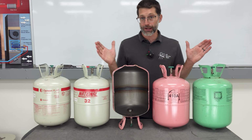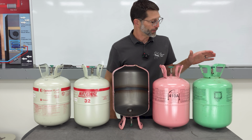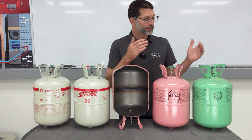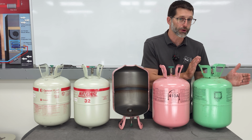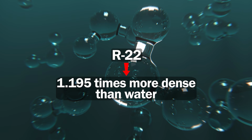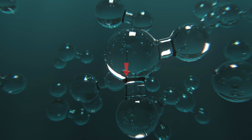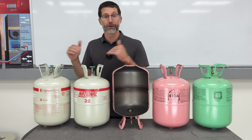And part of the reason for that is that density is different. So any type of tank, you figure the liquid capacity for a tank, you compare it to water. And so at 77 degrees, R-22 has this specific gravity compared to liquid water. It's 1.195 times more dense than water. R-410A is 1.062 times more dense than water. So these two are more dense than water. These two are less dense than water at 77 degrees.